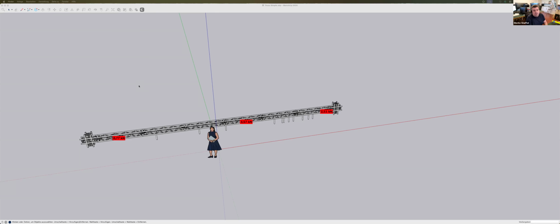We have done quite a lot of wind load improvements so that you can now also take into account the terrain category, which makes wind load calculations a little bit easier and more reliable. In the Layher support, for scaffolding, we have added a lot of new Layher cross sections. We have added the proofs for spindles and how much you can spindle something out, which is quite cool.